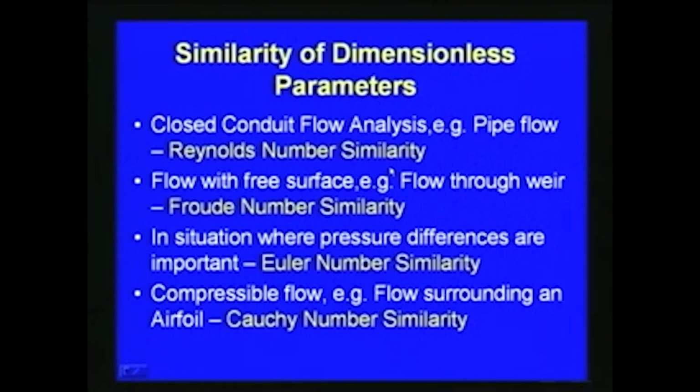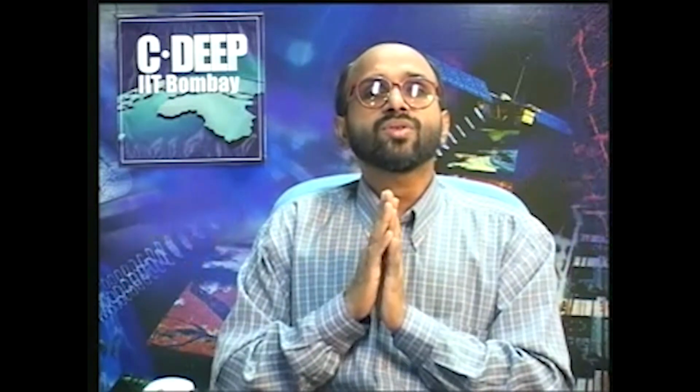Similarly, for open channel flow, flow through a weir, or flow over a dam or a spillway, the major force is the gravitational force. With respect to this, there will be a free surface also. In these kinds of problems, we model using the Froude number similarity.